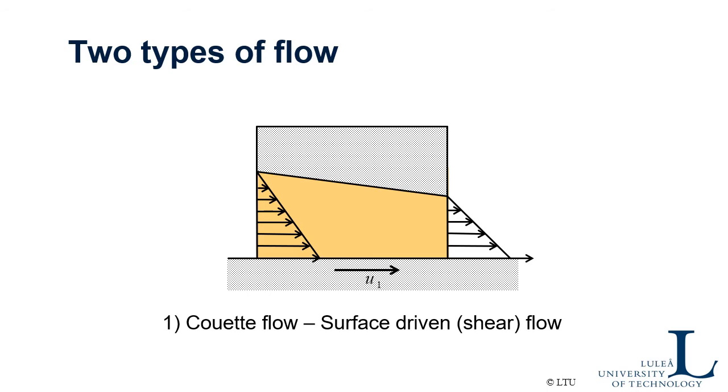We also assume that we have a Newtonian fluid, and the film is very thin, and for that reason we get what we call a Couette flow profile. So up here, on the stationary bearing pad surface, we have no speed, and in between those two surfaces we assume a linear speed distribution, which is correct in this case.